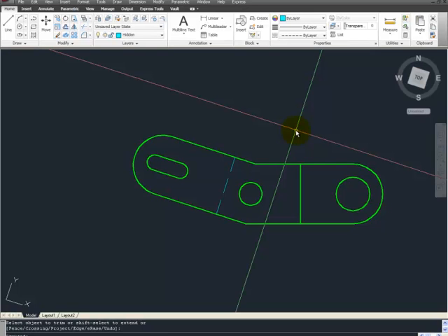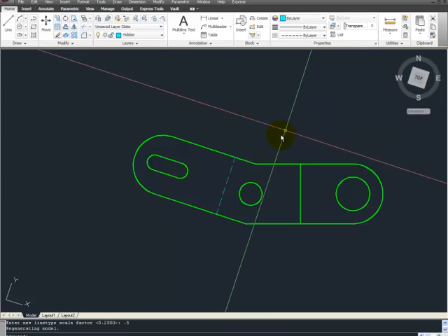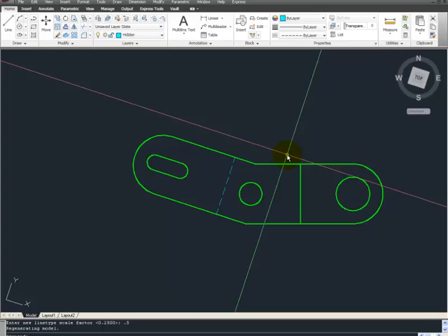I am going to change the line type scale here. So at an empty command line, I'll type LTSCALE, press the Enter key, and I'm going to type 0.25 and press the Enter key. The line type scale, or the repeating pattern of that line, seems a little too much, so I'm going to type LTSCALE again, press the Enter key, and change that value to 0.5 and press the Enter key. Visually, I like that a lot better.